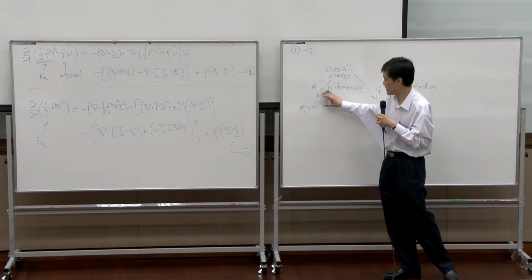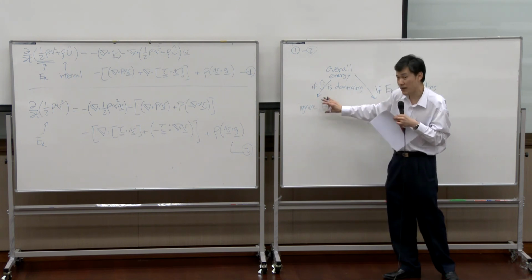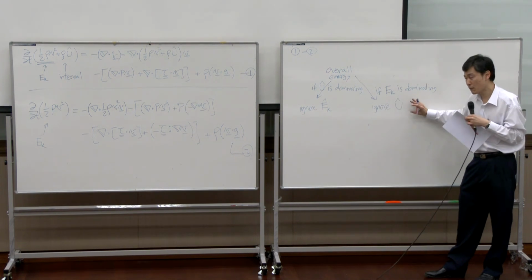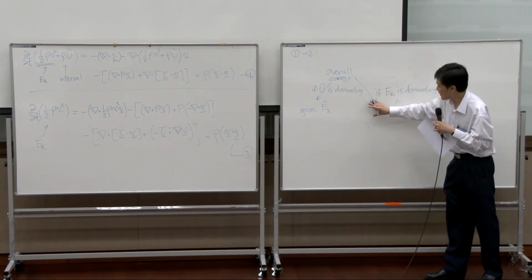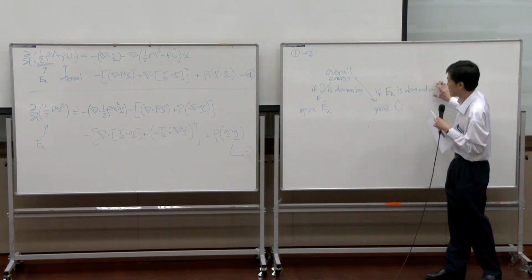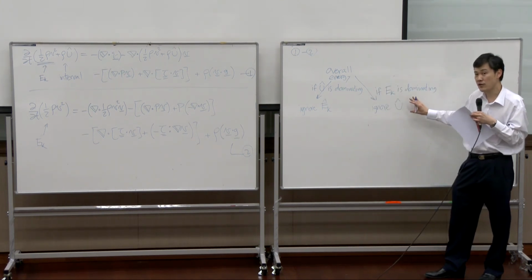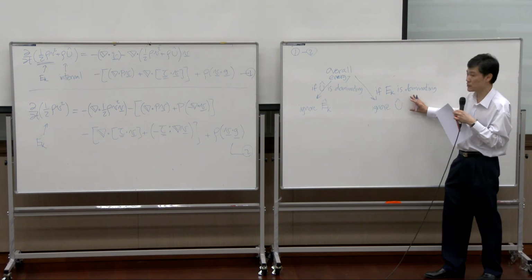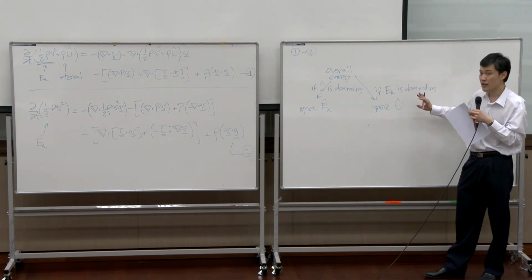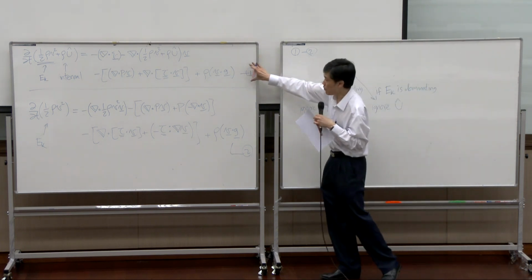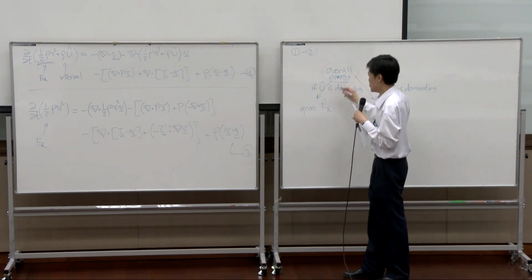Normally, thermodynamics ignore this kinetic energy or mechanical energy terms. On the other hand, if the system is isothermal, you can ignore internal energy and consider kinetic energy only. And this equation turned to be familiar equation called Bernoulli equation that you use in unit operation 1 or in fluid flow. Now, equation 1 on this board is overall energy.